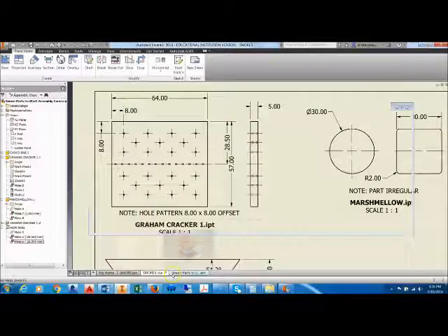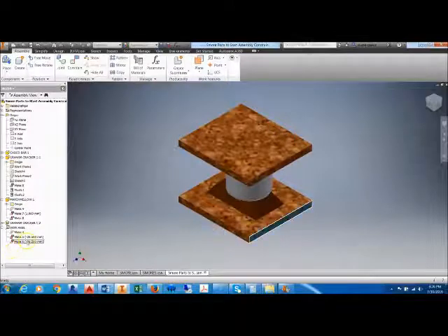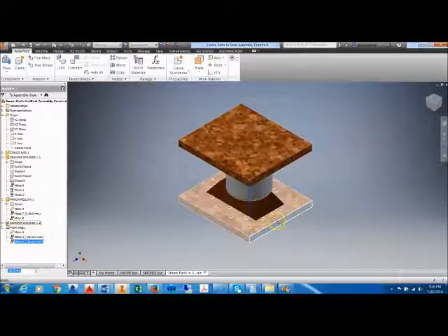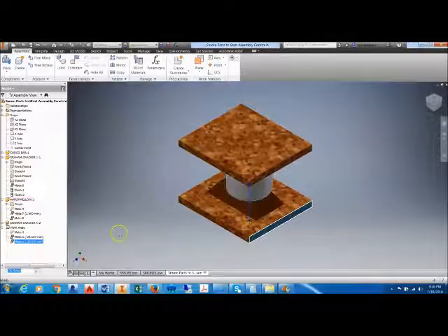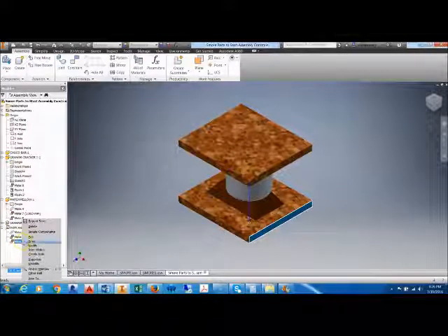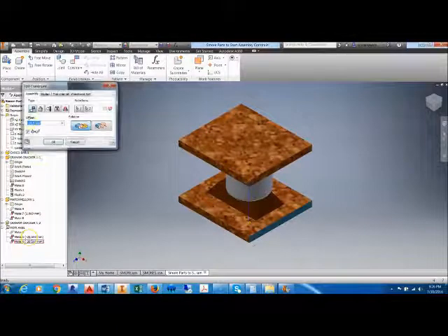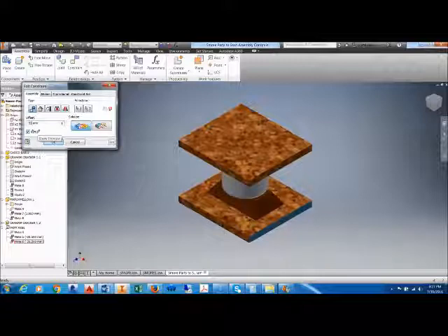So going back to the assembly, this particular mate constraint under the work axis shouldn't be 28.5. This side should be pushed in further. It should be 32. So I can right click on that, hit edit, and instead of 28.5, I can highlight and type in 32.